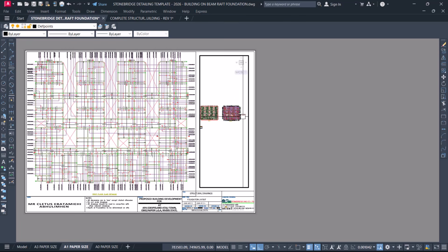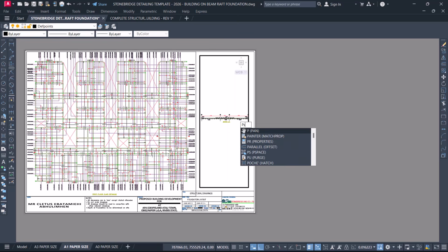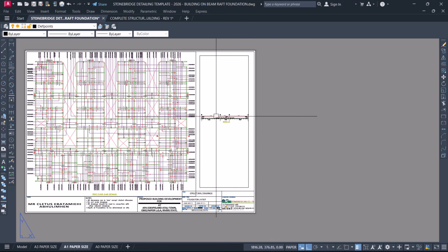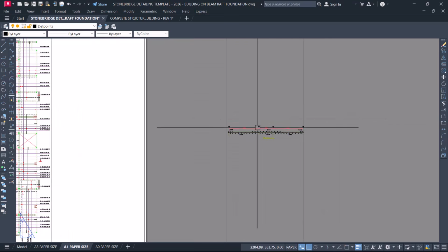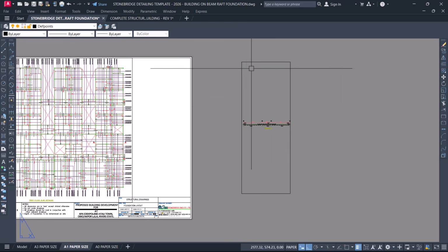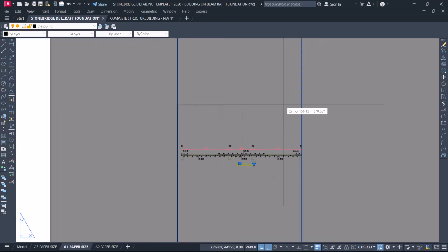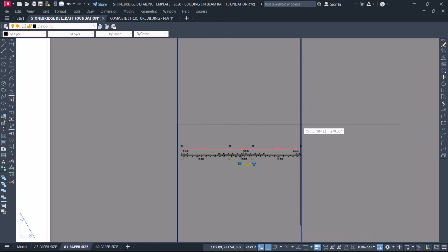At this point I need to rotate this particular drawing. I'll type PS to go out from here, enter, and click on this viewport. I'll move it out from this place first and keep it here. Now I will shrink this viewport like this. I want to shrink it. I'll click here and shrink like this. Just watch what I'm doing right now. Keep this like this, again come here, shrink again and keep this here, and again click here and keep this here.